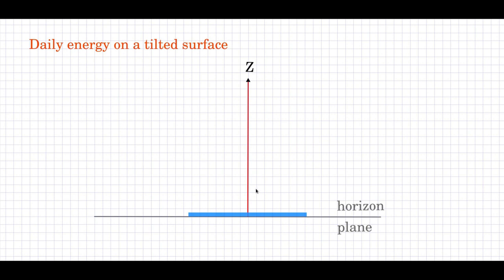Normally till now, we used to have a horizontal flat plate collector, something similar to this. And for this horizontal flat plate collector, we were interested in finding the amount of daily energy incident on it. But in general, normally the flat plate collector is not kept horizontal at the locality. It is kept tilted at an appropriate angle, which will collect the maximum amount of solar radiation.